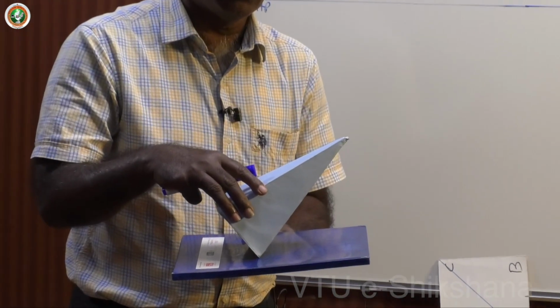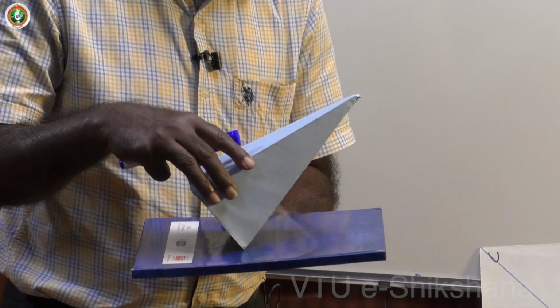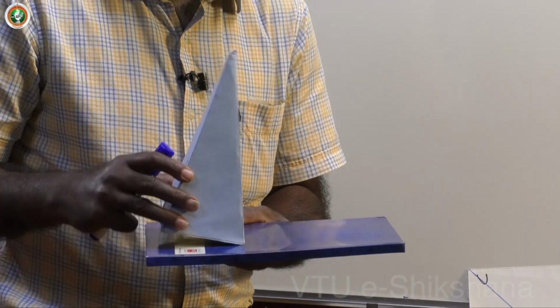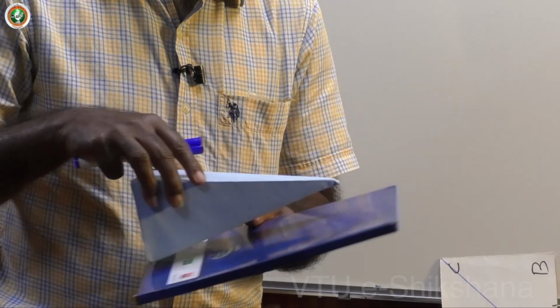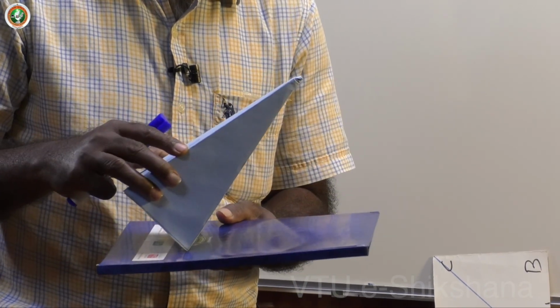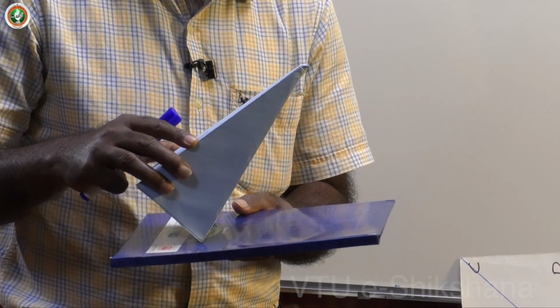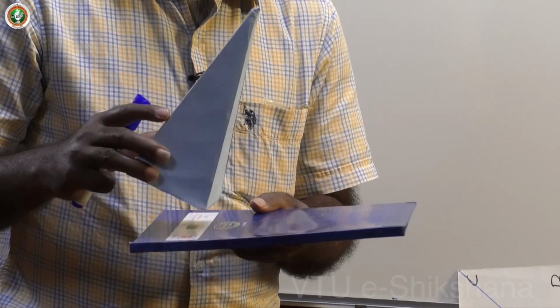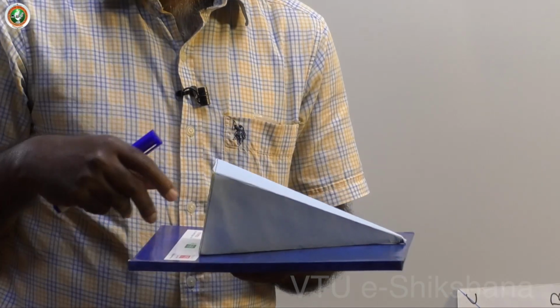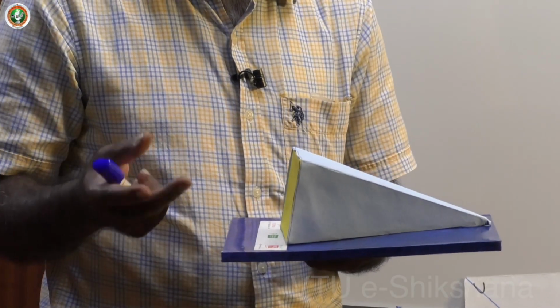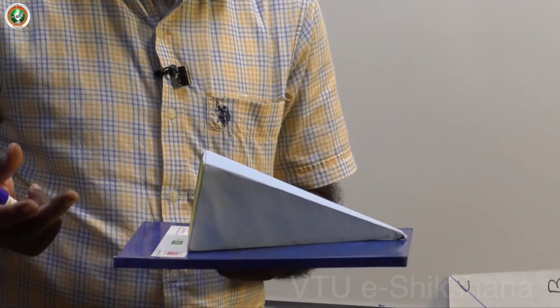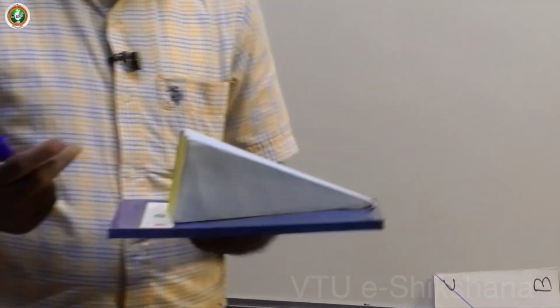Normally, we will have the base edge on HP, axis inclined at some degree to HP, or the slant face containing the base edge on HP inclined at some degree to VP, that you can do. But in this case, he says the slant face on HP. He never says it rests on HP with its base edge or corner. So, we have to decide what exactly the first position is.